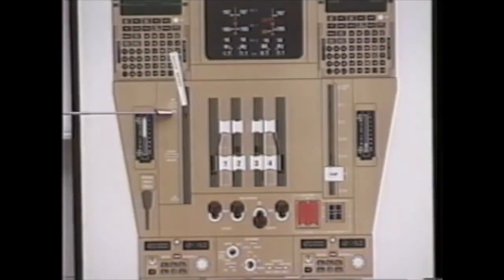Speed brakes for arm, pulling this handle up and slightly aft will arm the speed brakes for deployment. Two conditions have to be met in order for the speed brakes to deploy. Main wheels must be on the ground or untilted, and the throttles must be at idle. Once those two conditions are met, the speed brake handle will deploy all the way to the up position.